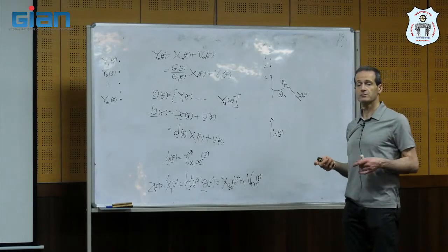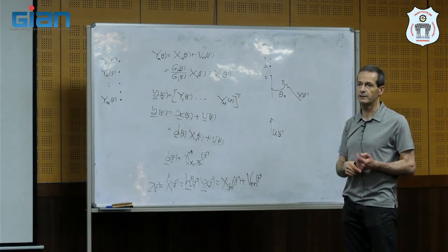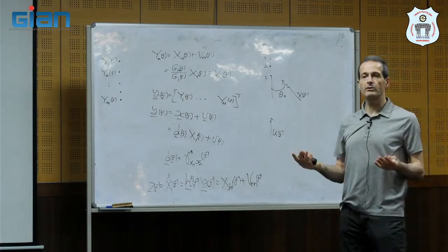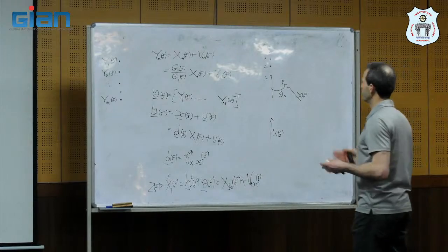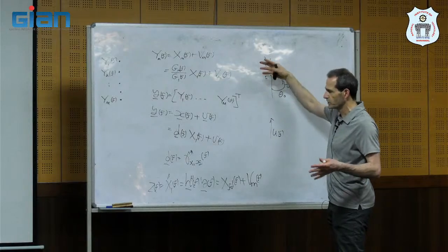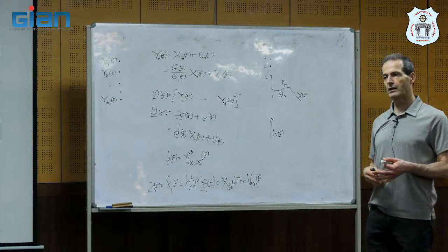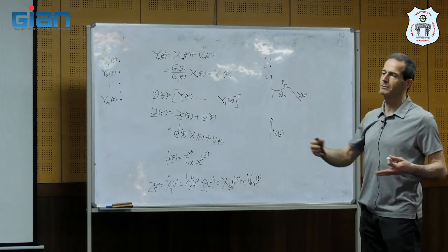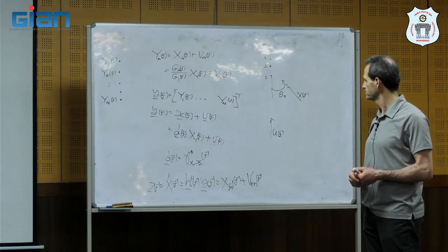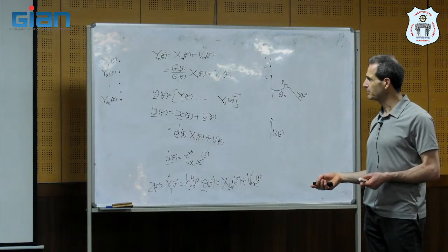But regarding the thermal noise, of course, we can reduce it to some degree. Not too much, based on the number of sensors. The power will be reduced inversely proportional to the number of sensors, which means that we reduce the noise by the square root of the number of sensors. So we can reduce, but it's not much. We need many, many sensors in order to average the thermal noise if they are independent.